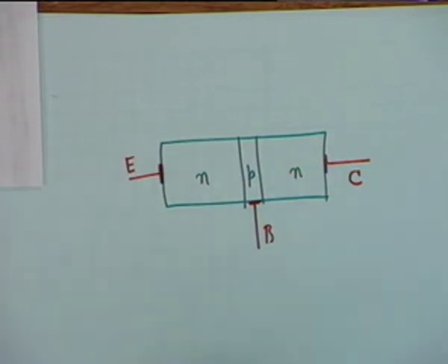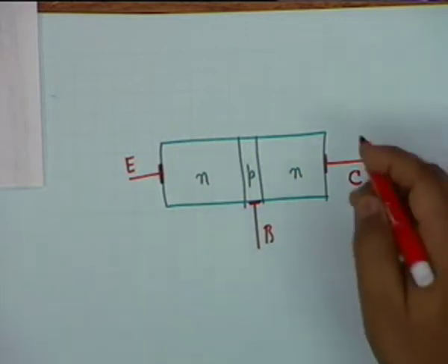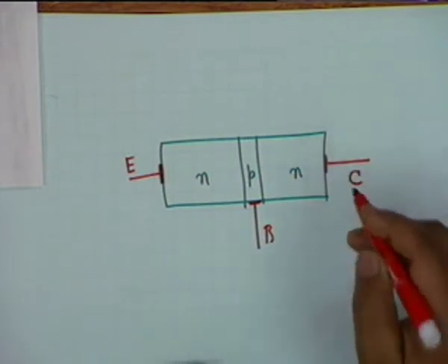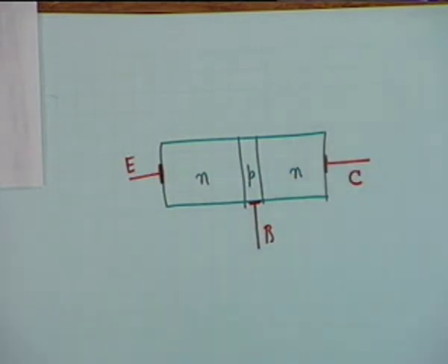What is the use of N plus? Okay. N plus is almost like a metal. All right. N plus is almost like a metal, heavily doped semiconductor, and therefore its conductivity is very large, and therefore it behaves almost like a metal, and then it allows a metal deposition very easily.